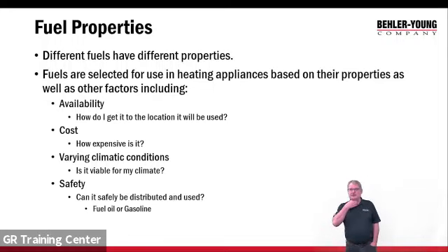Fuel oil. Now, some of you may use fuel oil. Fuel oil is a real safe fuel because you can throw a match right in a bucket of fuel oil and it's going to go out. You've got to heat the oil first. So the problem with fuel oil is as it gets cold, it starts to get thick. Some fuel oils in really cold climates you can't use without heating them.